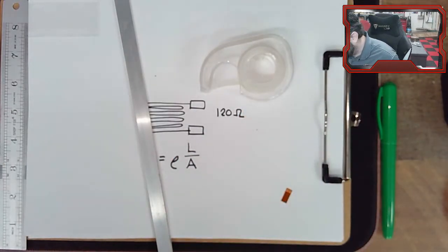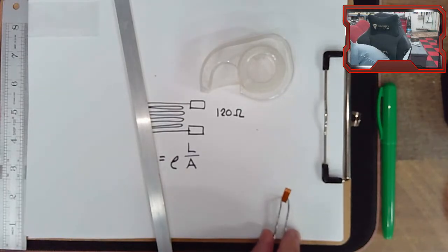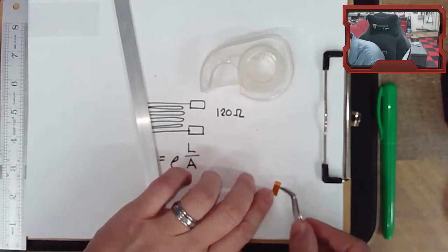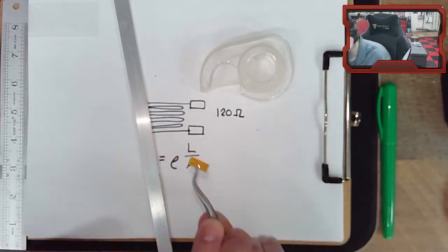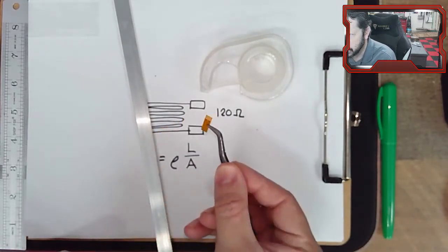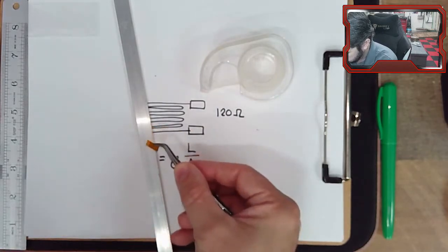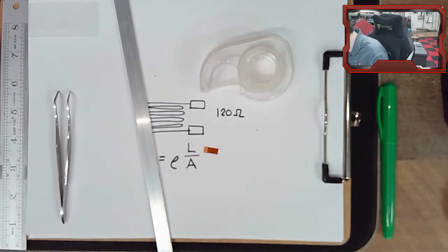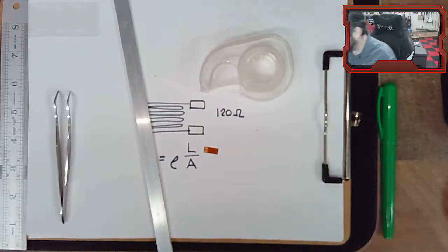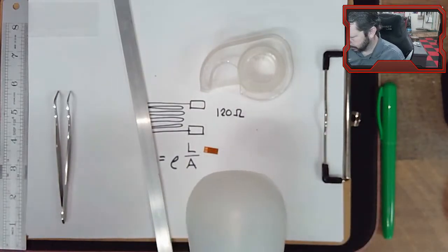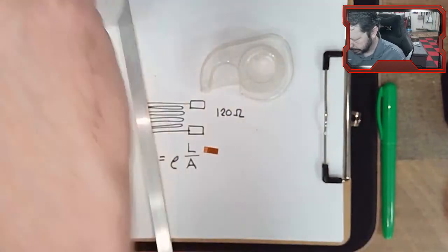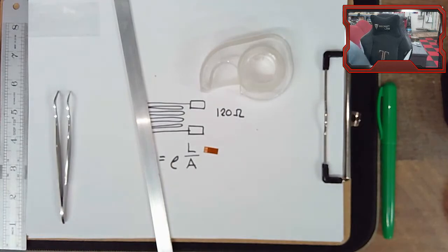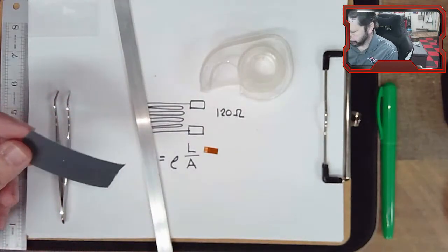We need the strain gauge, and we do need to make sure that we are putting it the right side up. Now, this particular one is pretty easy to tell the top from the bottom. The bottom is very dull compared to the top. I don't know if you can see that on the camera, but I can see it easily here. And I've got some IPA, so this is just isopropyl alcohol. We'll use that as a cleaner. And I need a little piece of sandpaper.